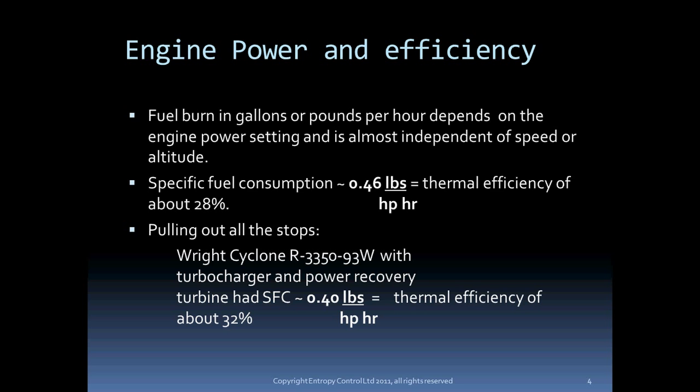Incidentally, the best commercial battery delivers about 0.1 horsepower-hours per pound, or conversely, you need 10 pounds of battery for each horsepower-hour of energy, as compared to less than half a pound of gasoline. So you can see why that electric aircraft is a bit of a challenge. You need 20 times the weight of fuel to provide the same power in an electric aircraft.